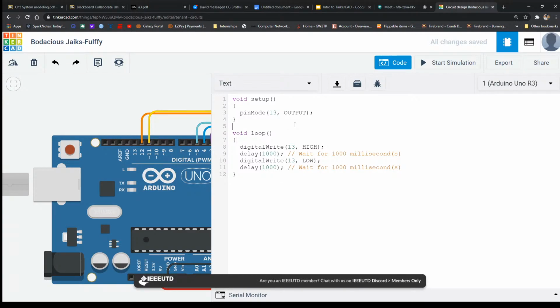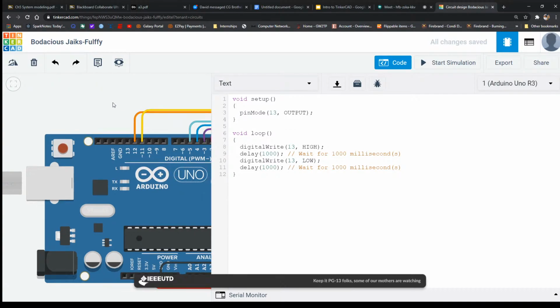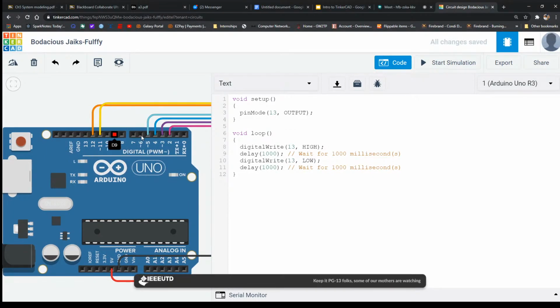So for Arduino, the basic code setup will have this function called setup. This is going to be setting up all of your digital pins, your GPIO pins, so in our case, these pins out here. And if you have any analog pins connected, you'll be connecting those as well. The setup essentially initializes all of those pins to whatever we've assigned them to.